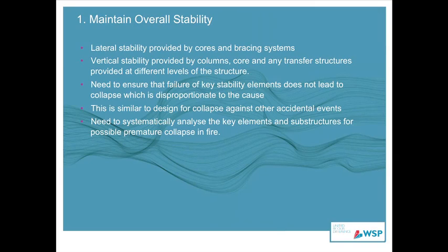So in terms of fire, what we really need to do is systematically assess, first of all, the building to establish what the key structural elements are. That is fundamentally important. In the existing prescriptive approach in the building regulations, there is no difference between a transfer structure or a beam carrying just a portion of the floor. And clearly that can't be sensible in terms of where we apply fire protection.